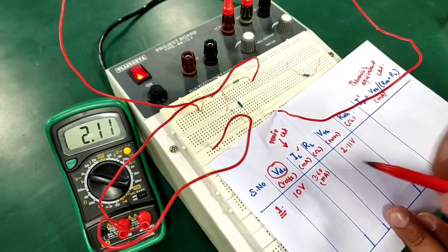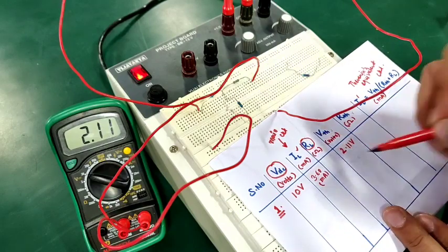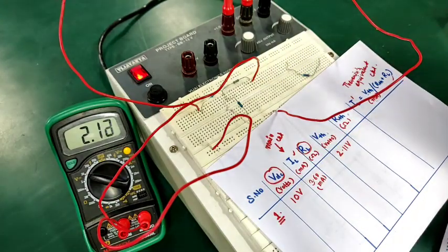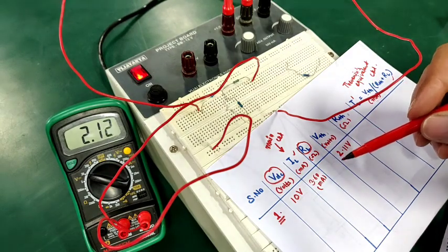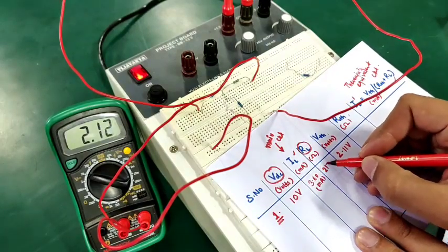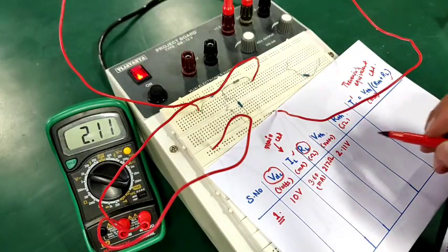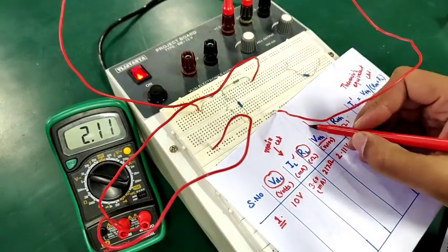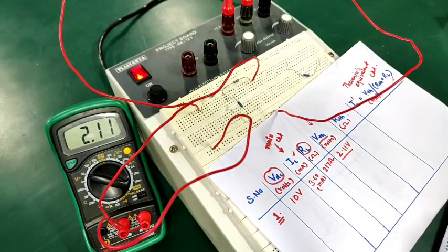Fine. You might be wondering that in the fourth column there is one parameter left, which is RL. You do not have to calculate RL now. Why? Because you did that in the initial step. Your fourth resistance, which was approximately 217 ohm, which you calculated in step number 1, will always be your RL, because you are not changing the value of RL here. So in this manner we have come to VTH, and our VTH is coming out to be approximately 2.11 volts.